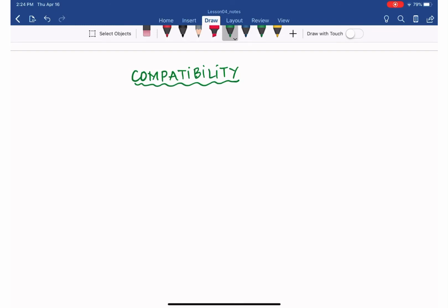With that, I want to demonstrate with a video, and we can go back to the lesson in a few minutes. This video shows the compatibility concept when we solve a problem that involves a statically indeterminate structure. A structure that is statically indeterminate is one where the number of equilibrium equations is not sufficient to solve for the unknowns, which are the reactions. So let me show that here.